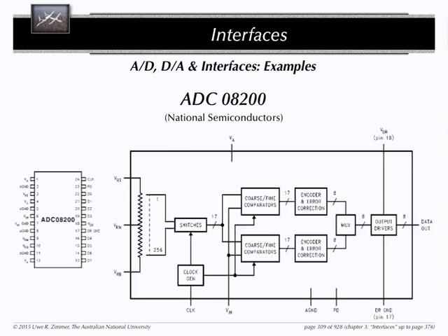The CPU has put this address out. In order to put data on the bus, somebody has to do that. This is not just taking a soldering iron and putting those 8 bits onto the bus. There has to be a controller in between. Those are device interfaces, and they have to be able to communicate with your main CPU bus. This device doesn't have that.